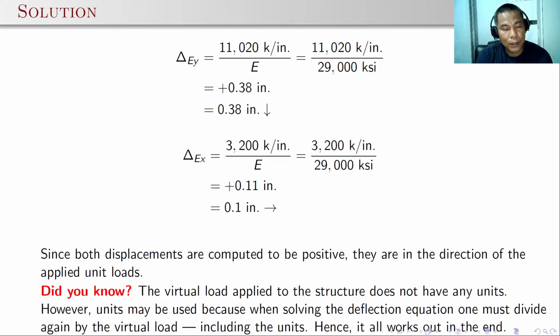Before ending this one, did you know that the virtual load applied to the structure does not have any units? However, units may be used because when solving the deflection equation, one must divide again by the virtual load, including the units. Hence, it all works out in the end.